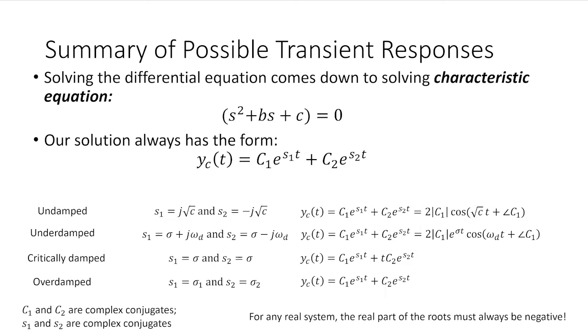Okay. So basically, for our second order system, in summary, we ended up with 4 different options for our transient response. It could be undamped, underdamped, critically damped, or overdamped. The one thing I'll say is that critically damped, in my mind, is sort of stupidly damped. I say that one's really kind of impossible to have. It's unlikely I would ever give you a problem where that is critically damped.